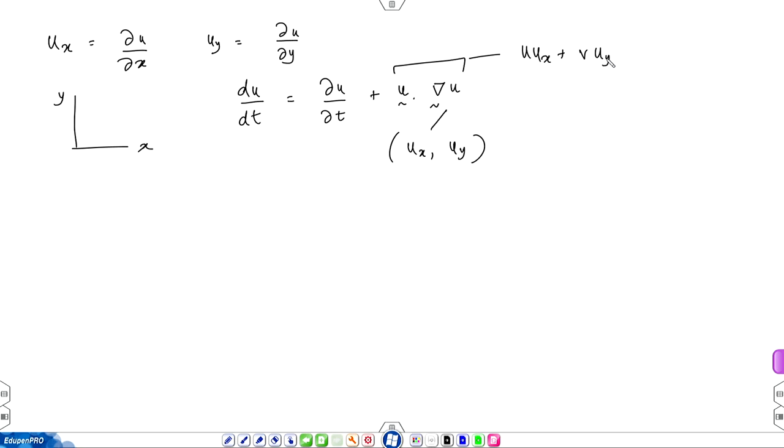It's your free will, so to say. So, the right hand side, similarly, the partial derivative of u with time is u at the same point later minus now, divided by delta t. Okay, so, it is along the time axis. So, the right hand side is easier to evaluate and is a preferred approach to solving fluid flow problems.